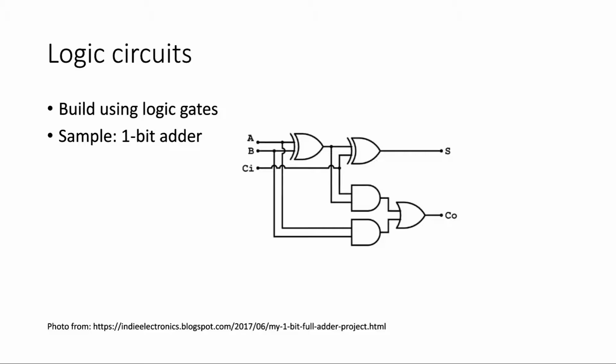But when it comes to computers, they need to implement it using logic circuits. For example, this circuit you see to the right actually implements the sum of 2 bits. So here we have 2 bits, A and B, each of them just 1 bit. And we sum them up together, and we have a carry bit.